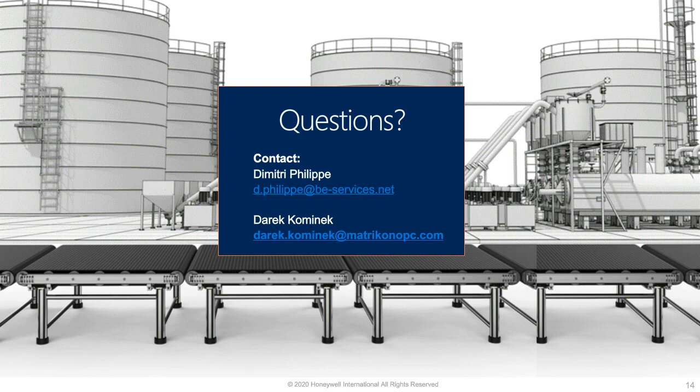Aside from the implementation of how you develop the equipment, as an end user, the options typically are that you have to find some mechanism to convert information into OPC UA. In your brownfield, basically existing infrastructure, you need to convert that into OPC UA and then move that data through your organization. That depends on the setup of the network, which in industrial settings is typically the Purdue model, right? Levels 1, 2, 3, 4, etc.